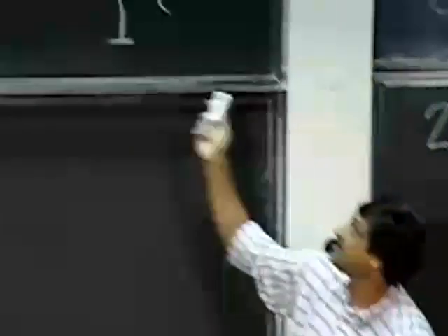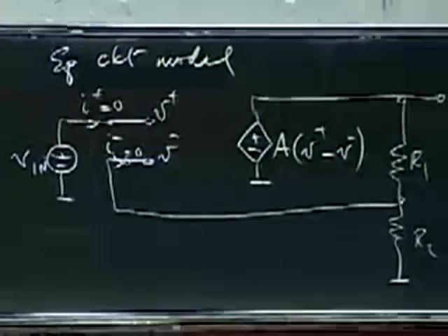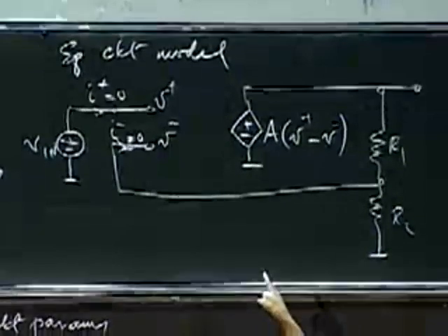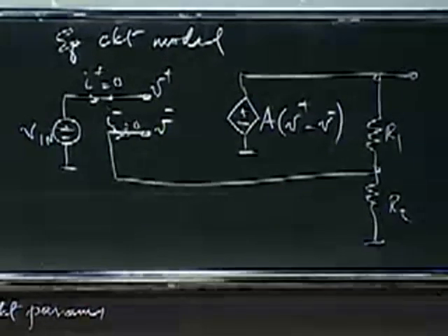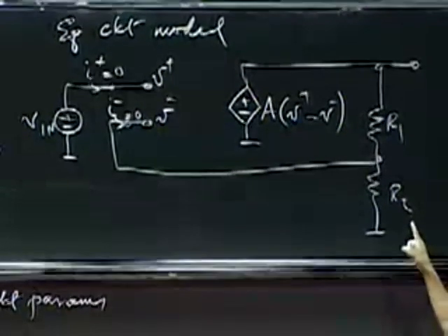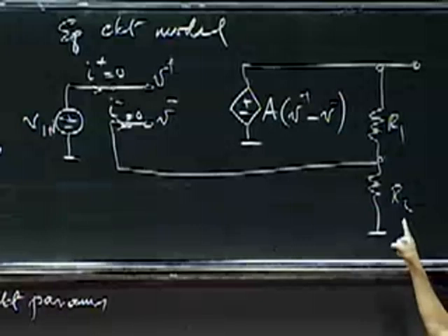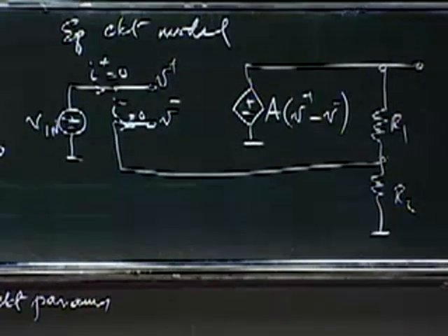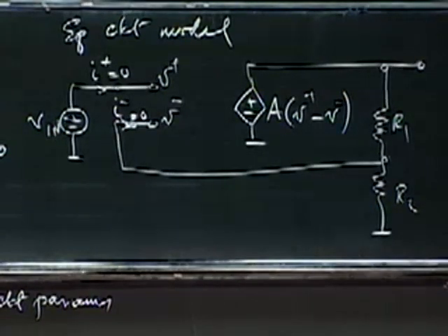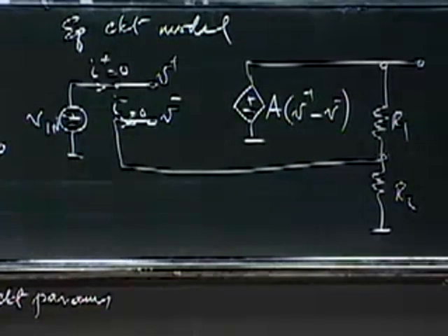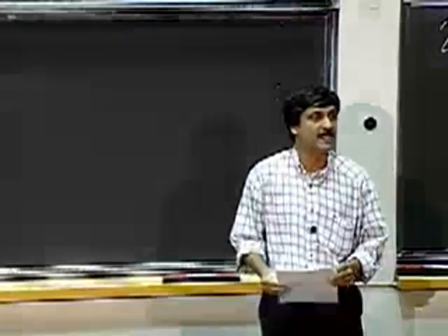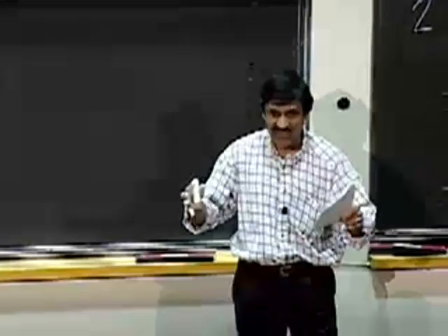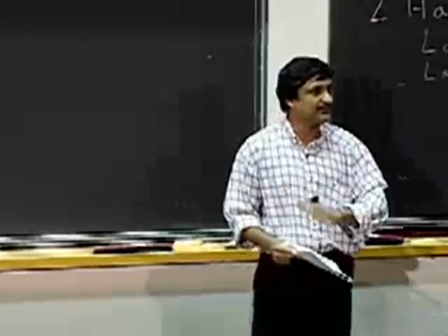So this circuit here, all I have here is one unknown node voltage. I know the voltage is V plus. I need to compute the voltage V naught. So there are two unknowns. V naught is an unknown, and the voltage here at V minus is another unknown. So this is a very simple circuit involving a dependent voltage controlled voltage source, and you need to find out V naught and V minus using the node method. Just apply it, it's simple. Don't freeze, just look at it and say, I can do it, and apply the node method. It will simply work.